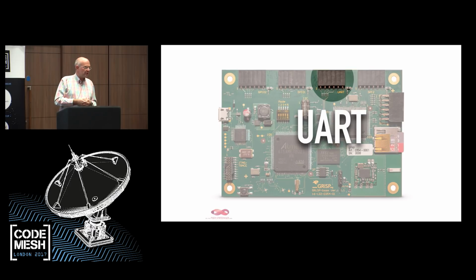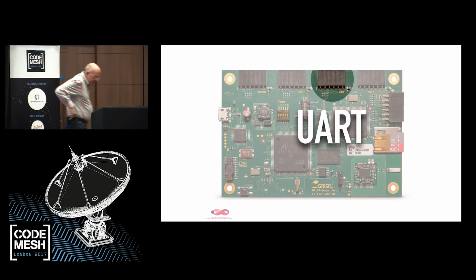And there are a few PMODs where you don't go all the way to 12 volts, but you directly plug it in, and the PMOD also talks 3.3 volt. For example, the ultrasonic sensor on the front of the robot, that's one of those UART plugs. It's hooked into the UART plug, you can see it here, and the motors are wired to the GPIO.